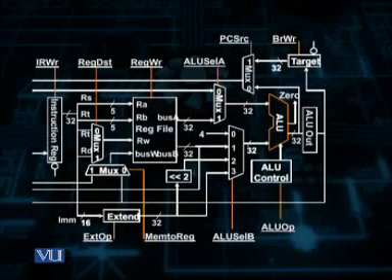This shift of 2 bits to the left, as I discussed earlier, even in the case of a single cycle data path, is performed in order to align the address at the 4-byte position, because our sample data path is designed for instruction words of 4 bytes in length.